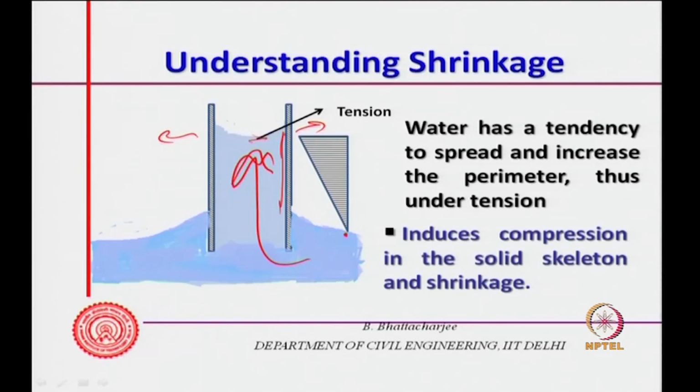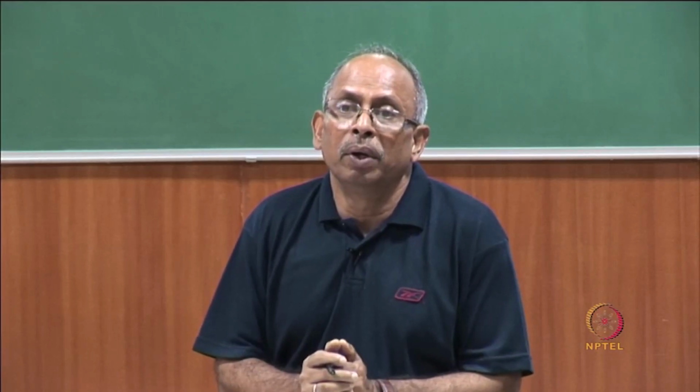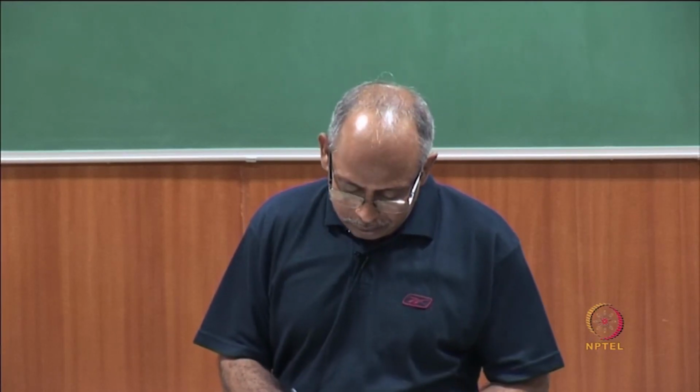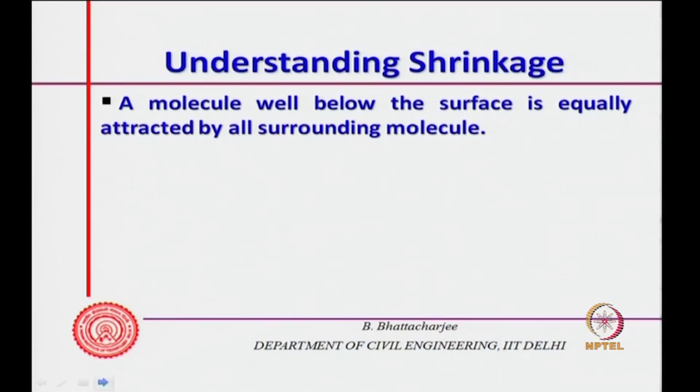Now, if it is within concrete or cement paste, then it will exert onto the paste capillary interface. So, the paste matrix or paste skeleton will be under a kind of compression, right. So, this will be under compression. Now let us look at this.